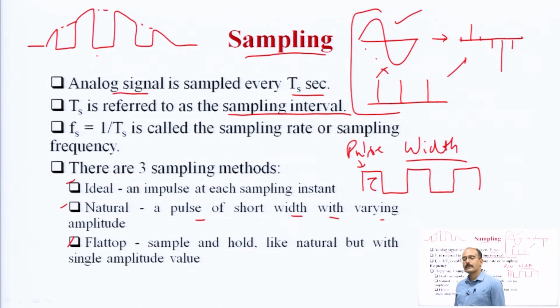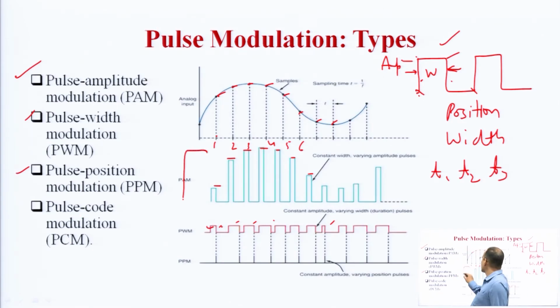But again there is a problem. Each sample have a continuous part on the top of the pulse. It means sample is not specifically giving you a sampled value. It has a group of values, and that is not fulfilling the basic aspect of the sampling. That is why we are using flat top sampling. The flat top sampling is same as this PAM signal.